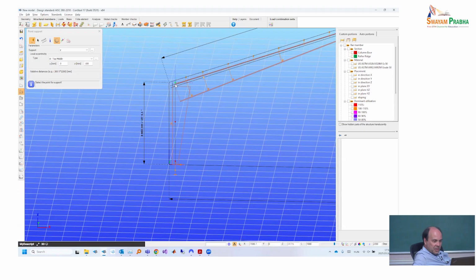If I do it from the reverse direction, then you see that the red point appears here at the higher position. The red point is now here. The point disappears automatically after 3-4 seconds. But it's very important, and that's very easy to make that mistake. So it's not just enough to say the distance, but you need to also show this way from which direction you want to measure the distance. So it's 1,500, and the other is at 3,700.